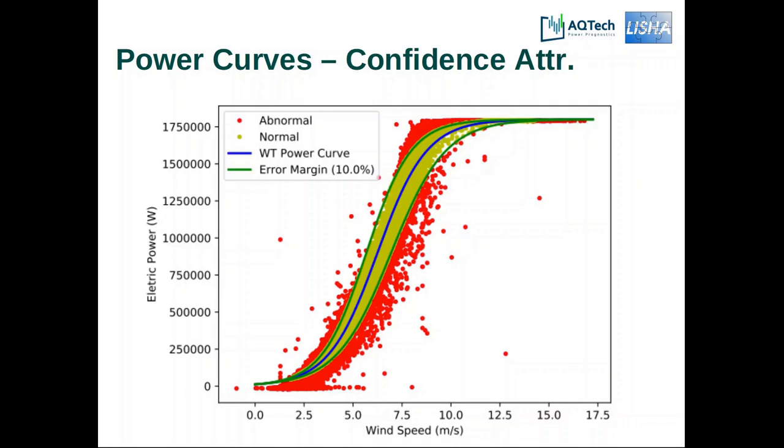Now, this picture shows the power curve after the outliers and low confidence data points elimination. Some distant points remained, but with a noticeable reduction. As the power curve model employed is one of the simplest, we can agree that a model that provides a larger tolerance interval will classify correctly more data points.